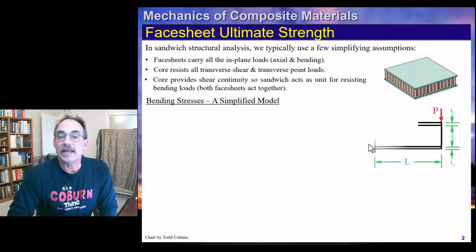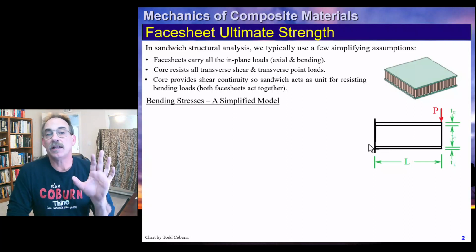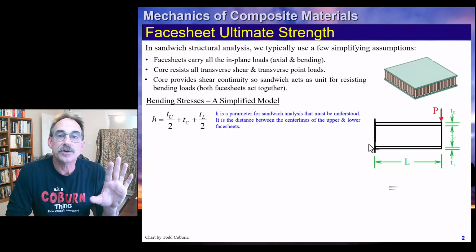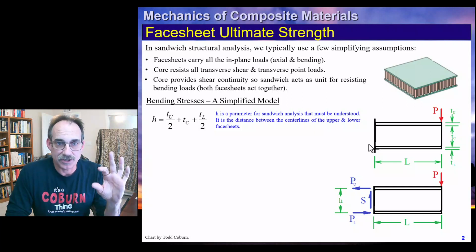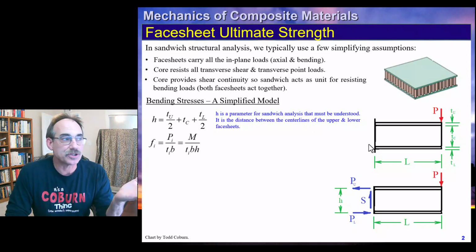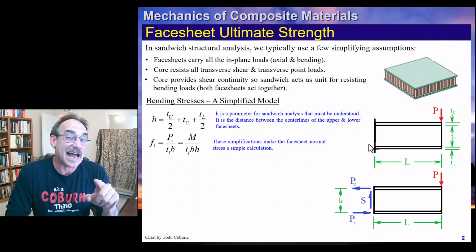We developed our simplified bending model following this approach, and we introduced some nomenclature, specifically our H parameter, which is the distance between the midplanes of the face sheets, and we calculated our stresses on that basis in the face sheets. You'll want to review the last lecture, lecture 13, if you need to refresh on those ideas.